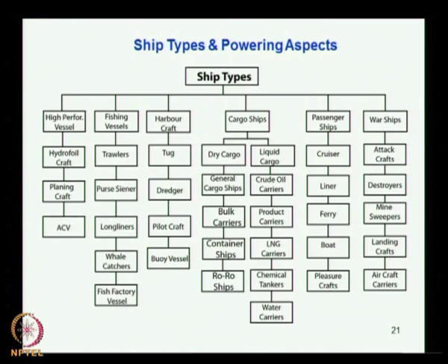You have to look into the type of vessel and its type of operation, whether it is going to have a single mode of operation, or like tugs it will have free running, or like fishing trawlers it will have free running and also a towing condition. So you have to look into the different operating conditions of the vessel, and based on each operating condition make a power estimation and go for the highest power required, depending on the type or stage of operation of the vessel.